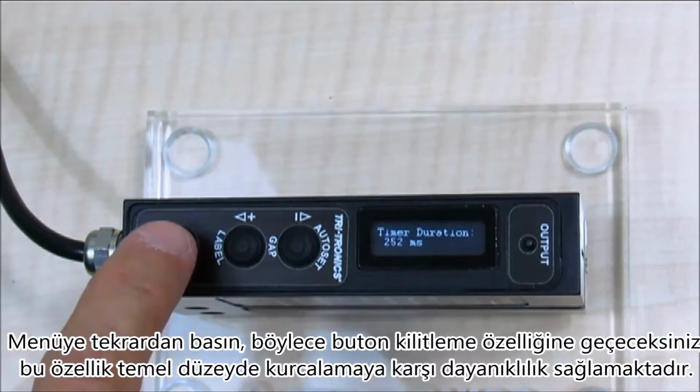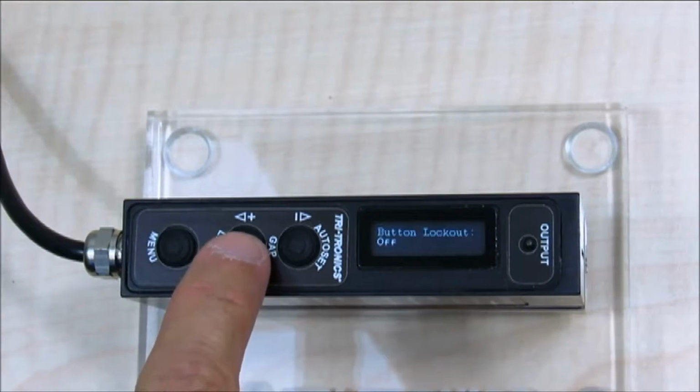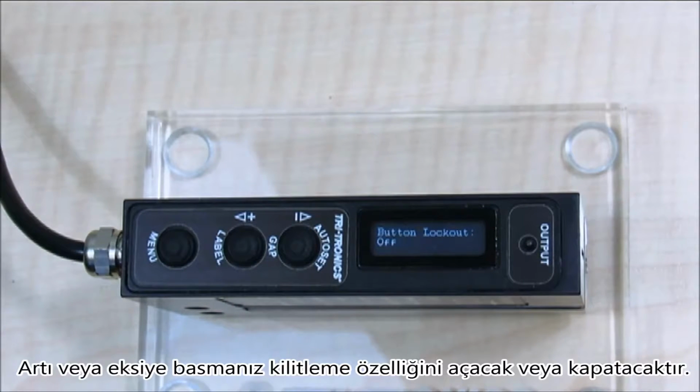Tap Menu again and advance to the button lockout feature. This feature provides simple tamper-proofing. The sensor will not allow any new auto set, manual adjustment, or option change while locked. Pressing either plus or minus will toggle the lock feature on or off.